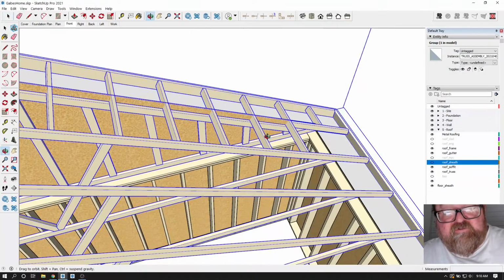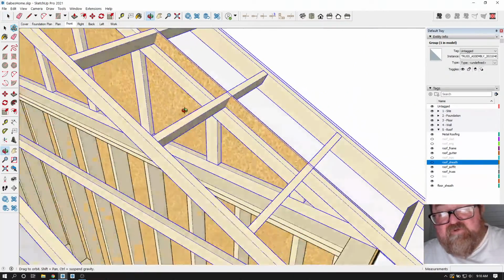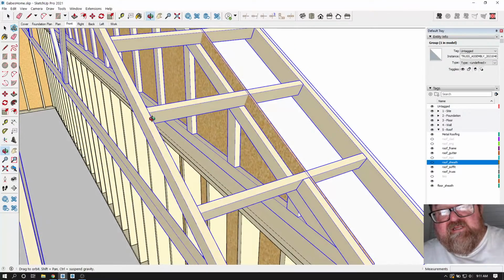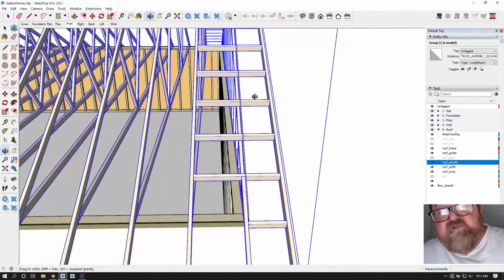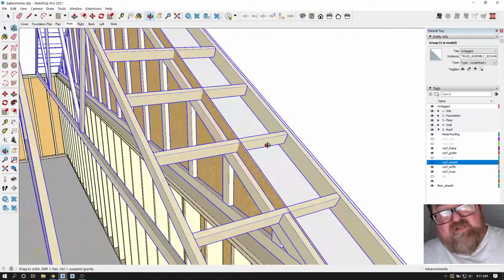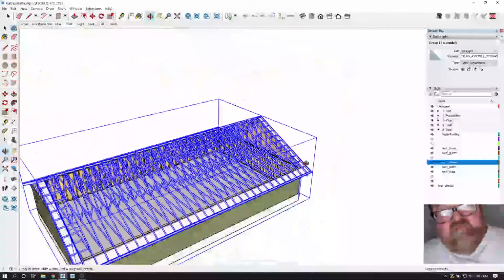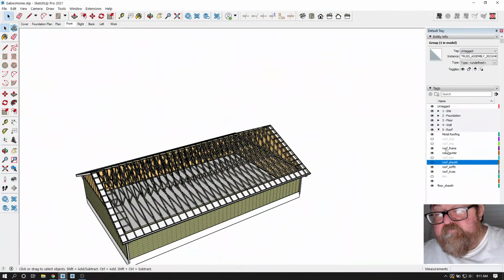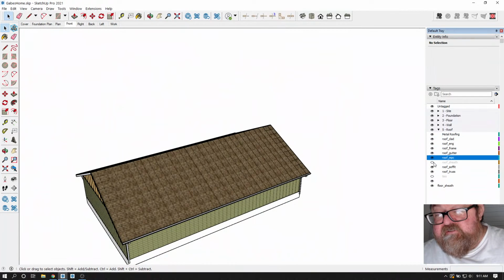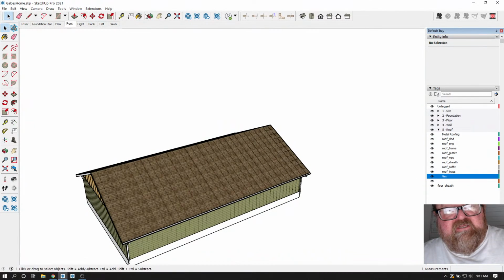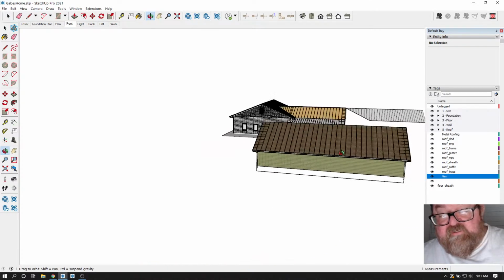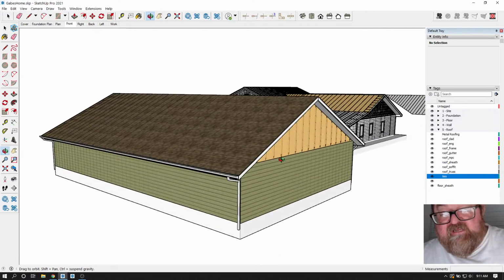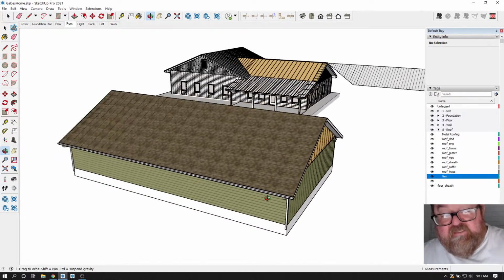See, and that's the strongest soffit in the world, where you have a drop truss and your outlooks sit on top of that and cantilever out. You can park a truck out here on your soffit, on your overhang, doing that. That's the strongest method. But the point is, he has all those options kind of built in. So let's go and turn all this stuff back on so it looks pretty. And you can also, there's separate cladding, siding, for the gable ends.